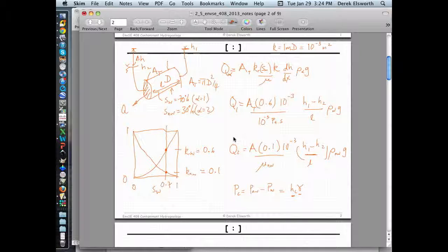And so you'd have two numbers that come out of this, and it would probably tell you that the amount of fluid that came out of the water was much more by a factor of a few, so 6 times in terms of the relative permeability than this case. Of course, you don't know what this is in that particular case, and it matters with these densities as well, which might vary by, if this is a DNAPL, maybe this is 1,500 kilograms per cubic meter, and maybe this is 1,000. So maybe by 1.5 to 1. But the biggest change would be in terms of these rel perms.